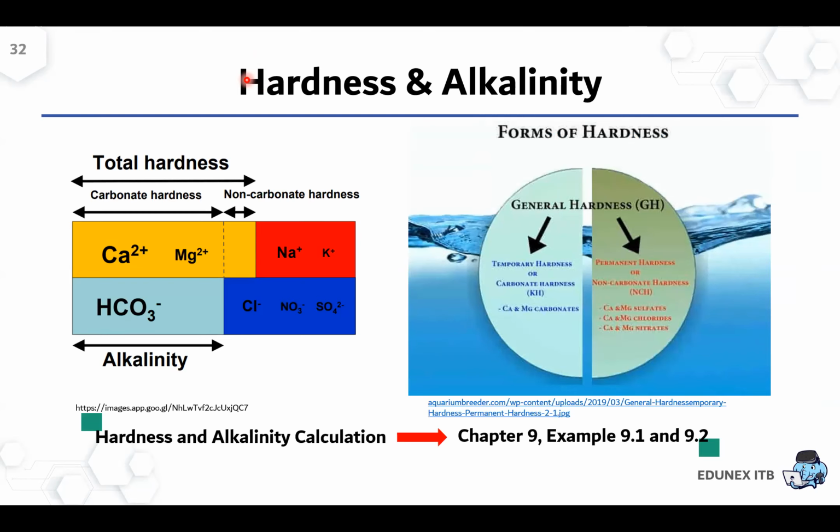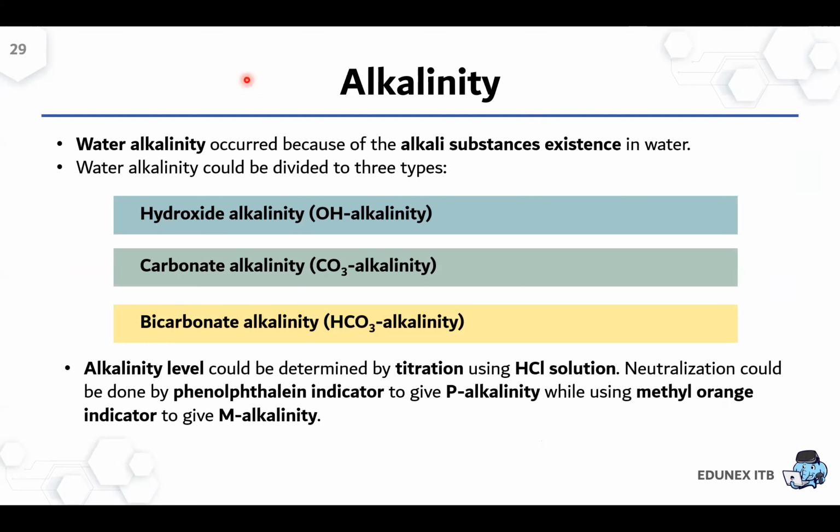The phenolphthalein will change the color to pink when the acid and the base mix, yeah. Phenolphthalein is actually colorless, and if it reacts, the reaction between the hydrochloric acid and the alkalinity, whether it's hydroxide base, carbonate base, or bicarbonate base, it will change the color from colorless to pink, yeah, while the methyl orange is used in order to get the concentration of the alkalinity.